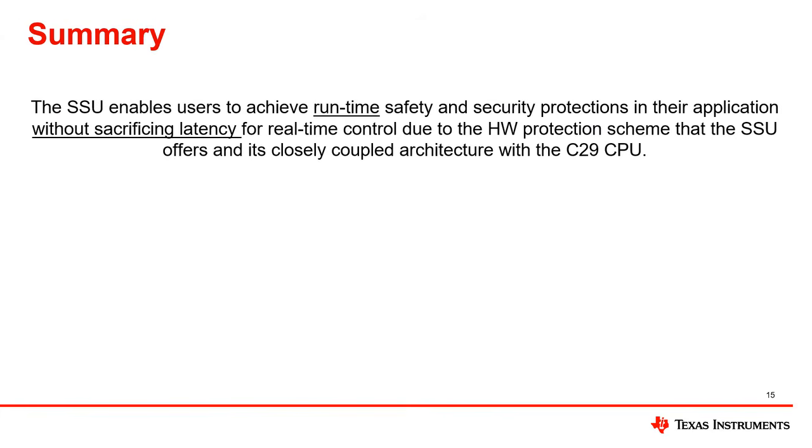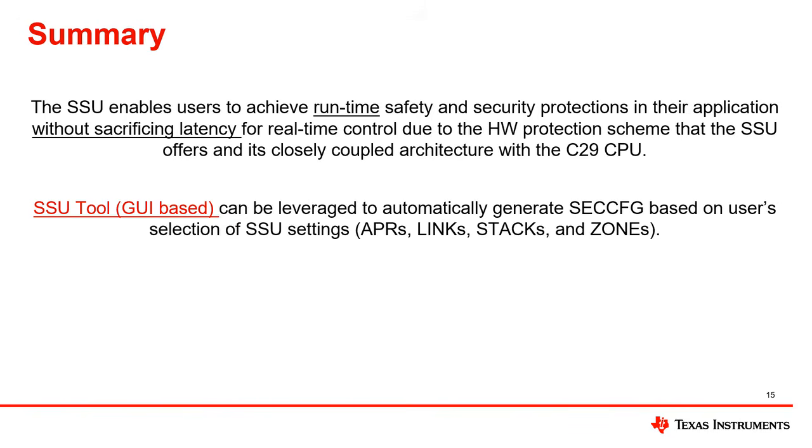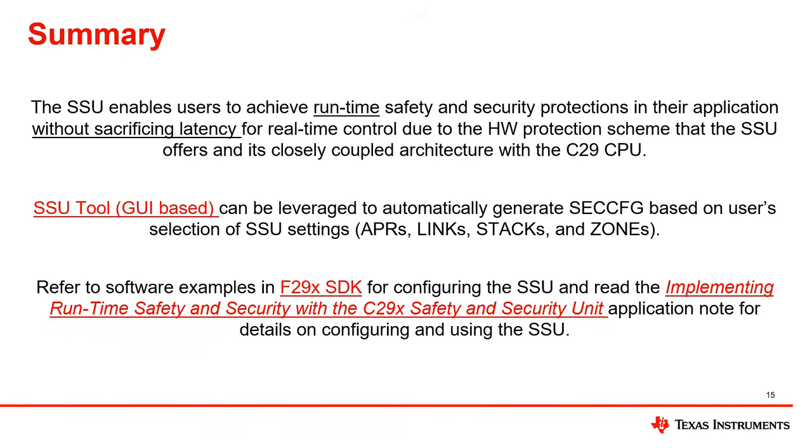Now, in summary, the SSU enables users to achieve runtime safety and security protections in their application without sacrificing latency for real-time control. And this is due to the hardware protection scheme that the SSU offers and its closely coupled architecture with the C29 CPU. The SSU tool can also be leveraged to automatically generate a SecCFG based on the user's selection of SSU settings.